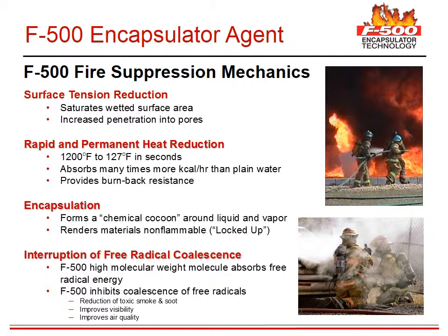Let's review the fire suppression mechanics. Surface tension reduction allows F500 to make water more effective by reducing the size of the water droplets and allowing the water to spread out, drawing the heat from every pore in solid fuels and better encapsulating liquid fuels.